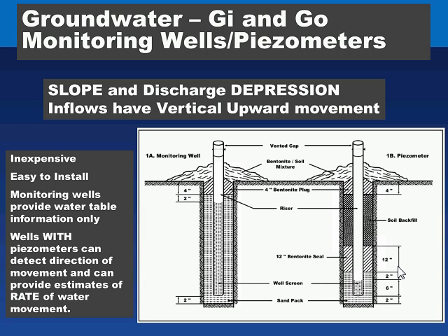Also want to talk a little bit about groundwater monitoring. Groundwater monitoring wells are a direct way to keep track of groundwater levels in wetlands, assuming we have enough time to collect that data, hopefully at least through one wetland hydroperiod. A monitoring well by itself will give us direct evidence of the free open groundwater surface.